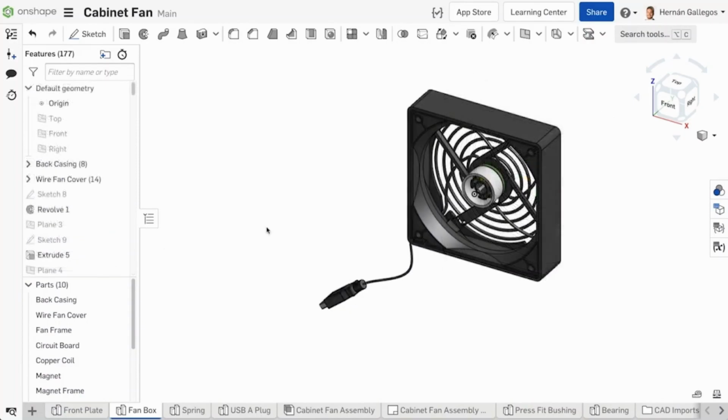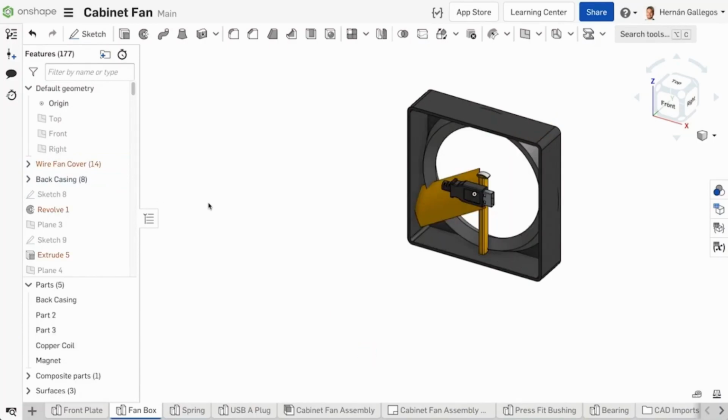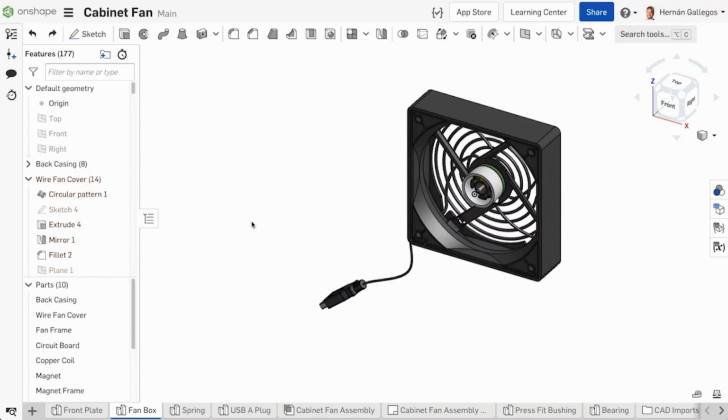One thing to note, when creating folders within the feature list, is the features and folders are order dependent. Features still need to be organized in the correct solve order to keep the parent-child relationship between them intact. Moving folders could result in features erroring if a folder with child features is moved above the parent feature. When creating features in a Part Studio, you can filter and organize a feature list to help with organization and understanding how features contribute to the design.